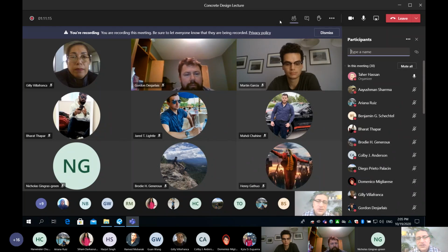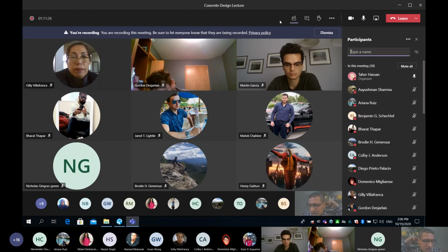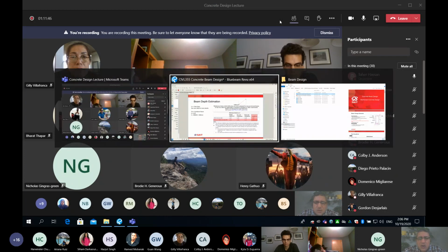Yes, true, guys, because simply the moment of inertia of your beam is connected directly to the height. And guess what? It's the height cubed. If you remember how the moment of inertia is related to the height of the beam, it is the width of the beam multiplied by the height cubed divided by 12. B H cubed over 12 for a rectangular beam. Which means the deeper the beam, the less the deflection. The deeper the beam, the less the deflection. Okay? And that's why you can see the discussion is all around deflection.